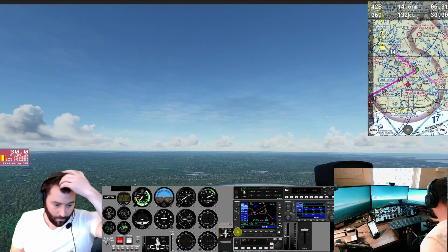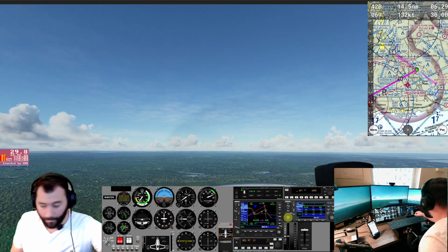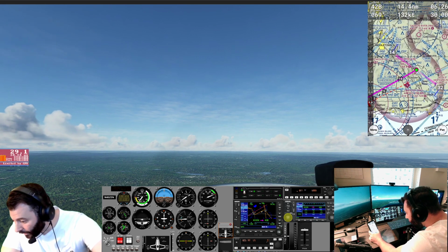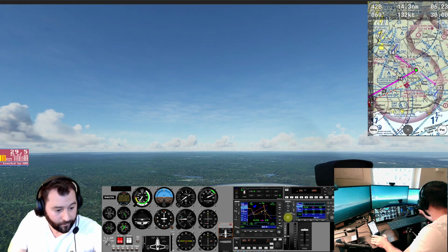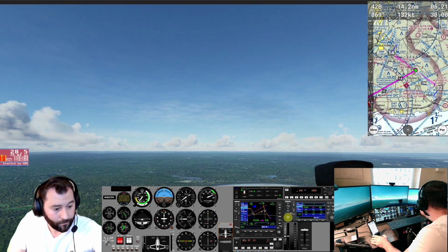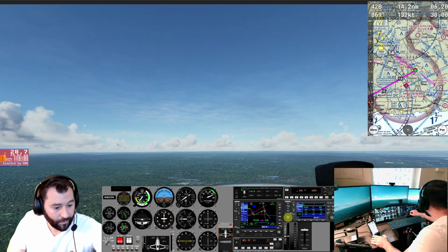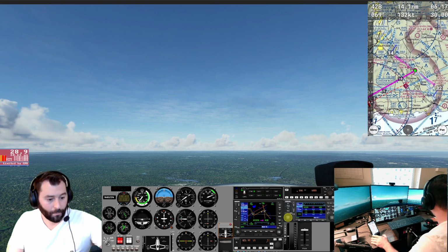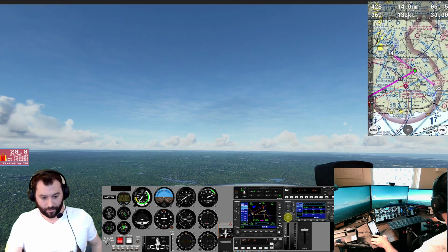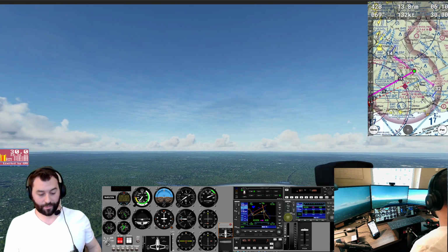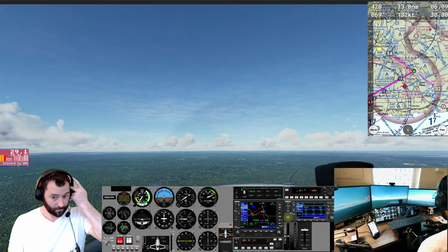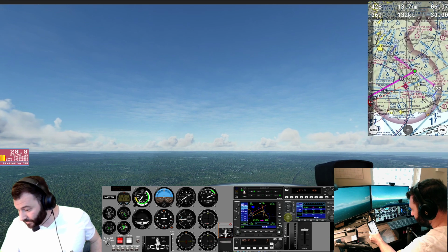Put that in there. And you know what we could also do? On our backup, let's put in Chester. That's 122.725. That way we're monitoring Chester, but we're talking to Goodspeed. We got 2 radios. It's easy enough to tune them with our touchscreen panel in the Knobster, so let's use them. We've got 6 minutes to go.